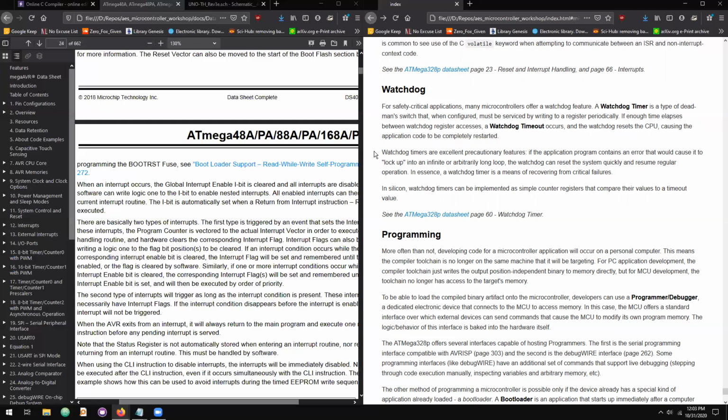And if your program gets stuck in an infinite loop, your microcontroller is therefore stuck. Your application is no longer functional. You're not able to respond to any external inputs. You're just stuck. In that kind of case, we can use the watchdog timer to denote that the application has ceased running, and so it's critically failed. In that case, we want to reset the entire system to make sure we can recover from that kind of condition.